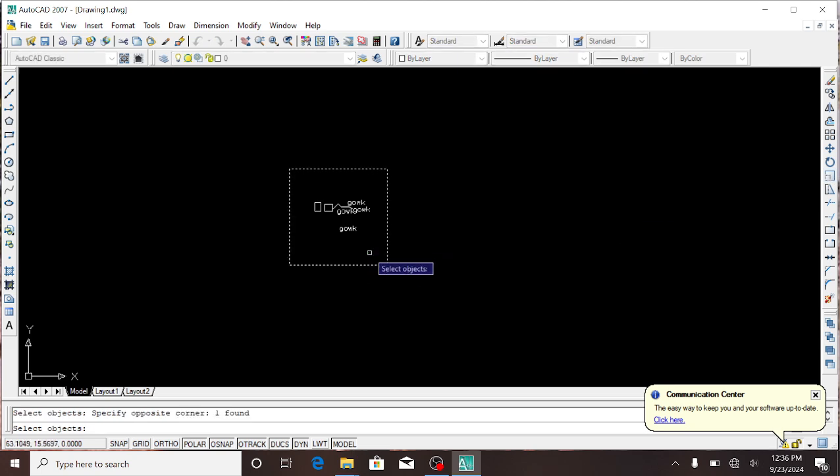You can scale something downward or you scale it. So what you have selected is scale. What you do is select the object that you want to scale. Then you right click. After right clicking, then you pick the point where you want to scale it from. Then you can drop it and scale. But you can also type the scale factor.